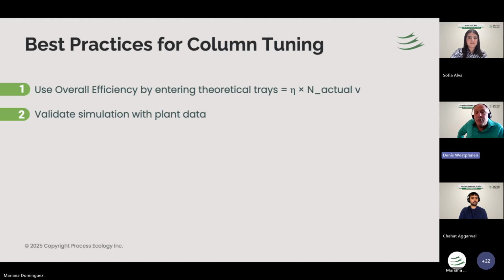Oh, and one additional piece of information: when you go to some reference books, for example, there's a famous book by Gerald Kaes on modeling refinery units, and it shows a table with typical recommended tray efficiencies. Those tables give the overall efficiency, not the tray efficiency that you just punch into the simulator. So watch out, because the results are not the same. These two types of definitions do not result in the same outlet conditions for your column. That's the bottom line of this entire webinar.